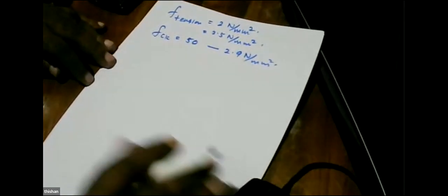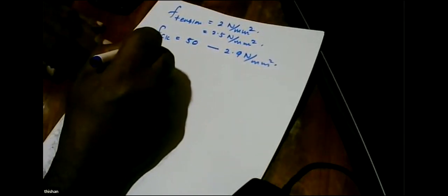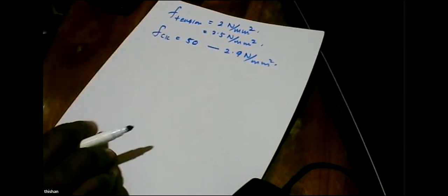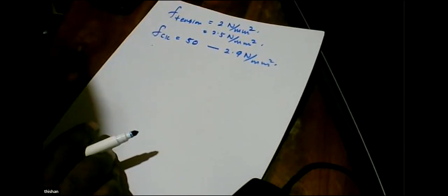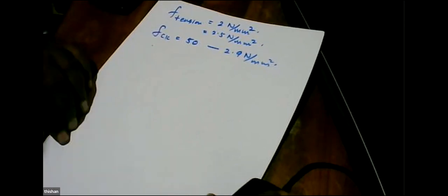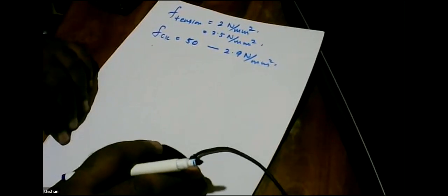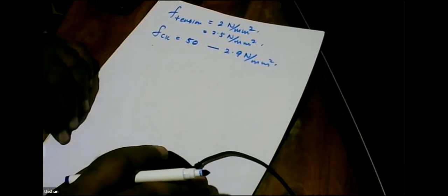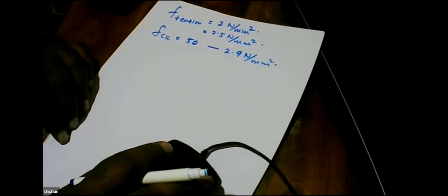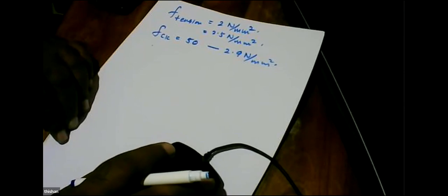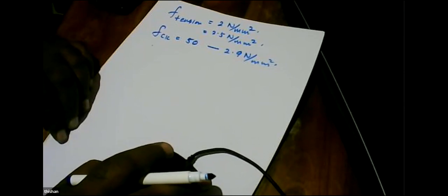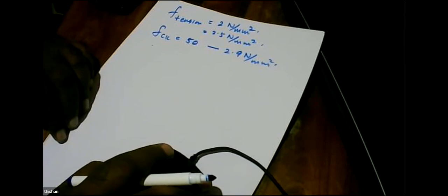Then we also have to see, now we are talking about 40-50 concrete, and in that one the allowable tensile stress is about 2.5 megapascal.